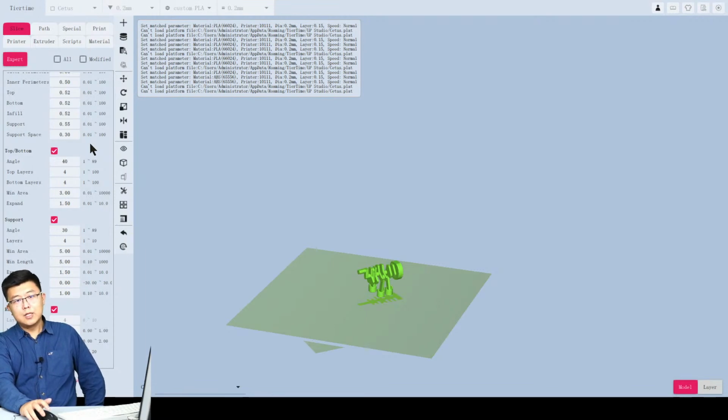So for now, if you have a thin wall with two perimeters, and in the gap you found there's an empty gap there, this is due to the fact that the gap width is not a multiple of the path width. Therefore, either the printer will fill up the gap, or it will leave out the space that is not a complete multiple. I hope you understand what I'm saying.